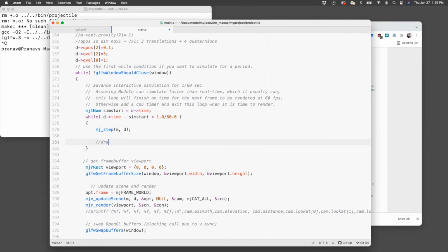The drag force model I used is equal to minus C times velocity squared, so it's proportional to the square of the velocity, where V is the magnitude, times a unit vector v. It has to be given to each of the 3 directions, so it's going to be C V squared, but acting in the x, y, and z direction of the velocity. That's why the unit vector.